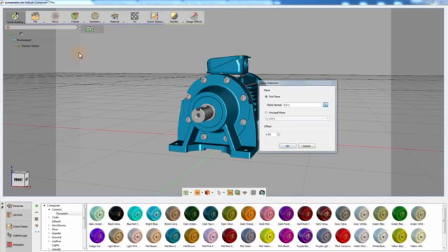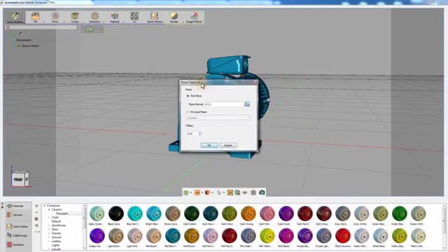The Plane Selection dialog will appear. In this dialog, we are going to determine the plane on which we are going to create the annotations. Selecting the proper plane for the annotations creation is crucial in terms of where the annotations will be projected for viewing. Since we are going to add measurements for the front side of the design, we need to select XZ plane or simply click on a parallel face to the front view.